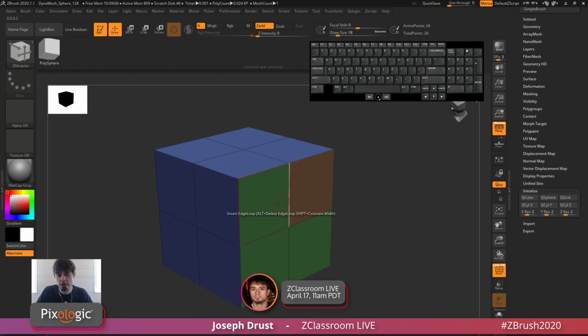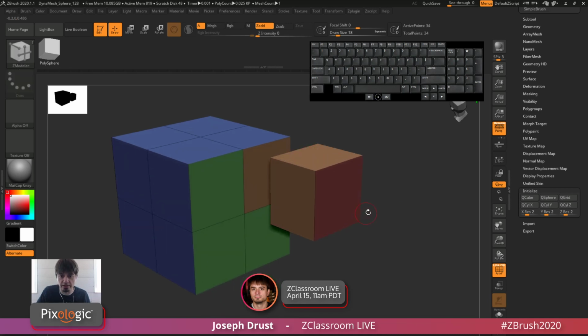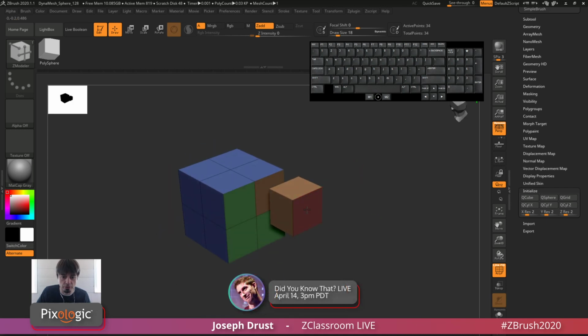So with the Q mesh, the edge loop and the point, you may think, okay, that brush has 3 options, right? There's a little bit more. Some of these options have modifiers as well. On the Q mesh one, if you extrude the poly out and hold down Control, you'll be able to break that face off. This allows you to pull it out, and now I have a floating island of geometry, and then I can Q mesh that and generate a new kind of part.